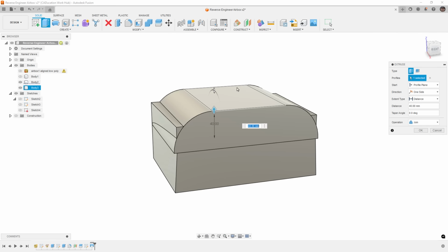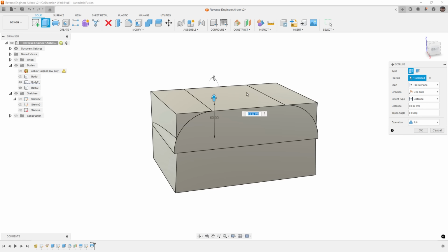And then we can bring back this other body and essentially say, go up to this face. So this allows us to extrude or add the geometry to this. The downside to this is that we won't actually be able to carry that angle. So it's basically a straight line up front of plane on the front of this thing, and then this angle is going from tapering in to going straight up. So this is one way that we could do it, but then we're going to have to, again, do a loft and kind of cut things away.